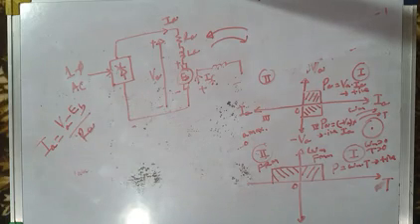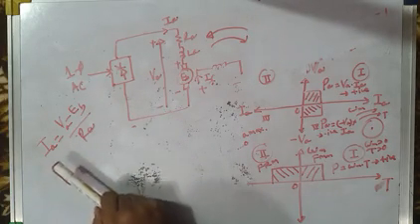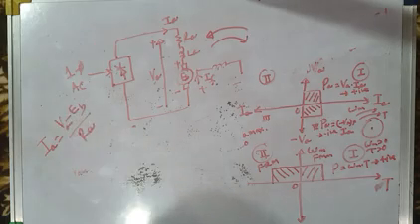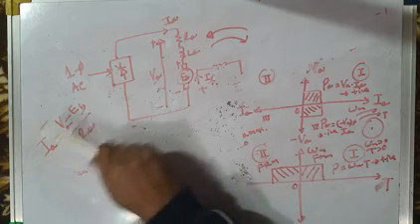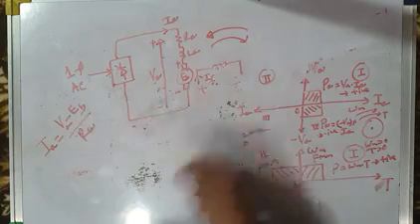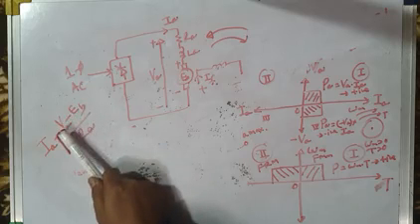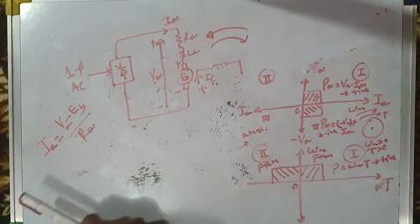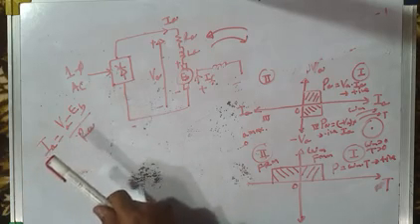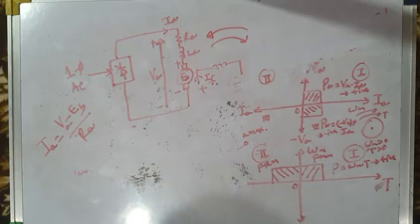In the previous lecture, I explained that regeneration will occur only when back EMF is greater than VA. When VA is greater than back EMF, current is positive and it is forward motoring mode. But when EB is greater than VA, current will be negative, and negative current means the torque is negative, and negative torque means forward regeneration mode.